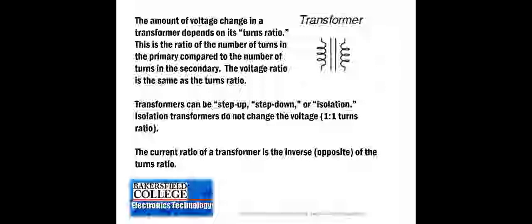Okay, so remember that the neutral terminal A, which is found where C3 is, is the neutral, and at some point is grounded. And then the 65% tap, or the lower voltage tap, is where C2 is. It creates the same voltage at the secondary, but you don't have the neutral associated with it. You don't have the ground associated with it.